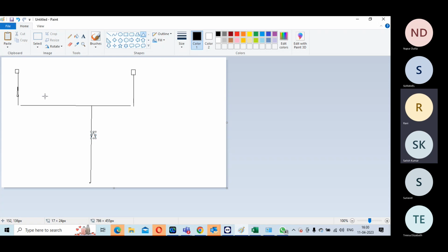So from one master clock, I'll go to connect to the mux like divided by 2. From there, I have generated one generated clock. From there, I wish to do the clock balancing for the registers. Is it right, sir? Sorry, from master clock, I will be connecting to one clock gating and then it is connected to the one mux. From mux, again, it will generate the generated clock. From the generated clock, again, it will build the clock tree to the leaf cells, registers.